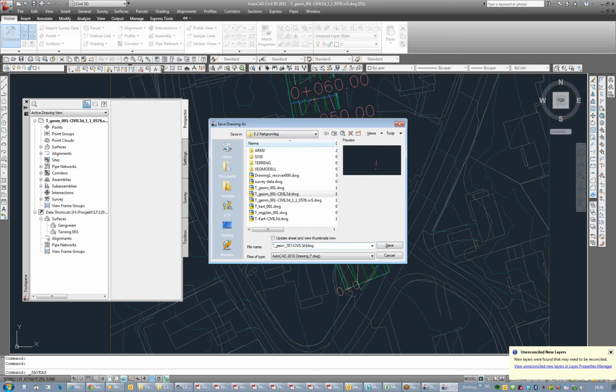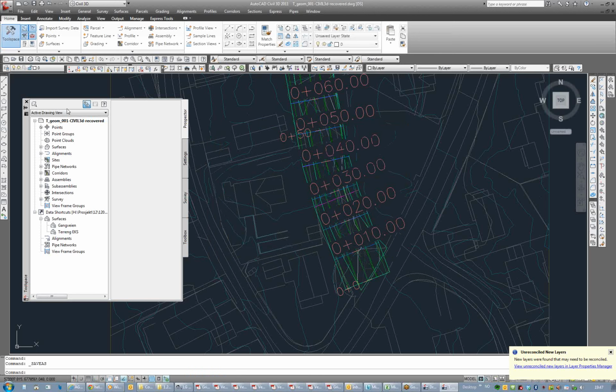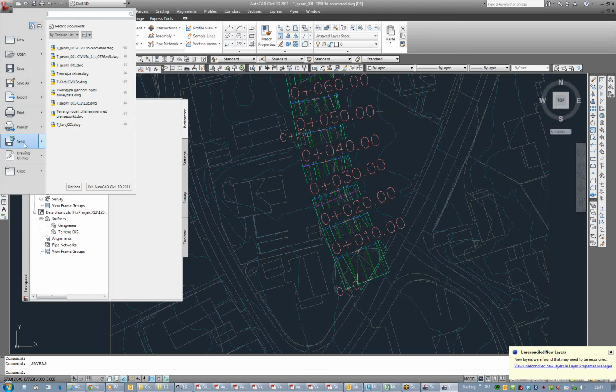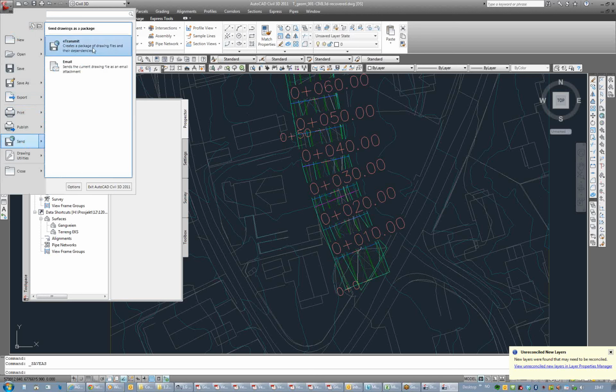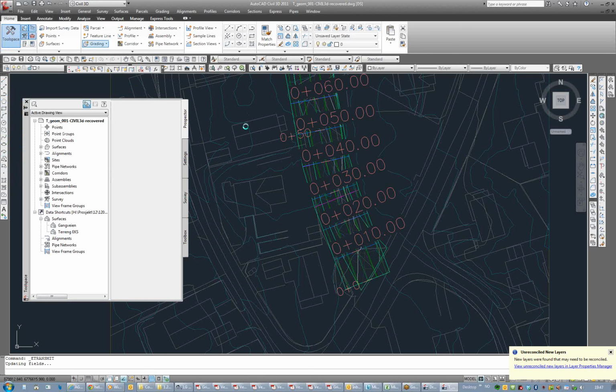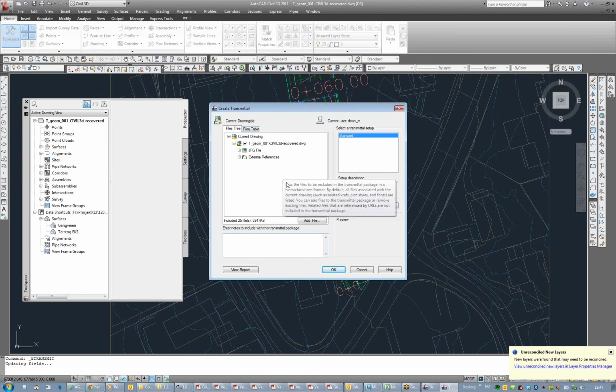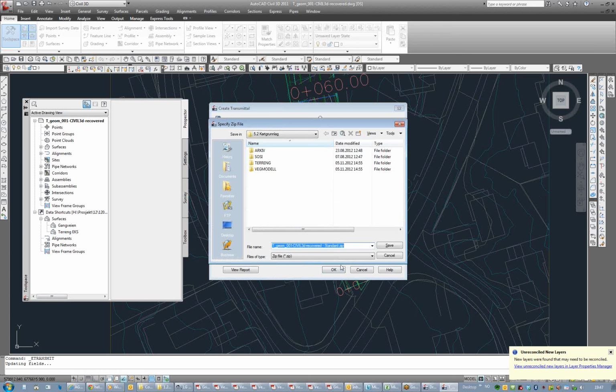Okay. Yeah, and then just do an e-transmit and upload it to the Dropbox, and I'll go in, because the process we went through is the process you normally go through to get your sections. But it's coming up with a 0 elevation, so I've got to figure out why it picked up the wrong elevation.